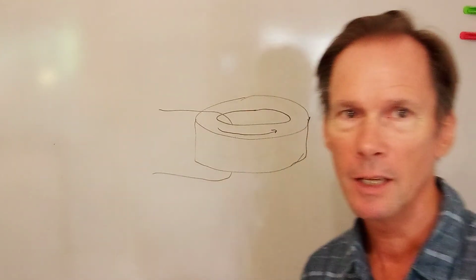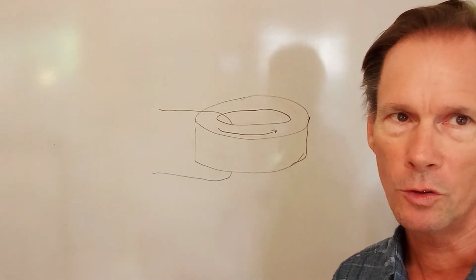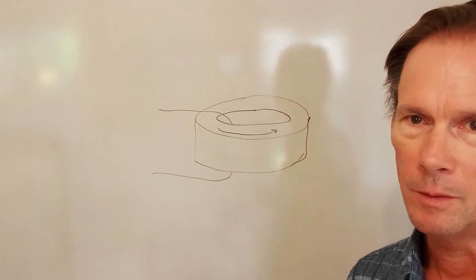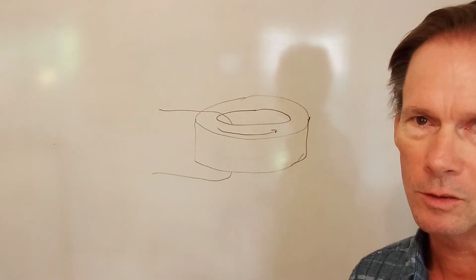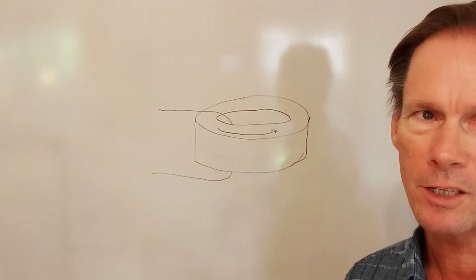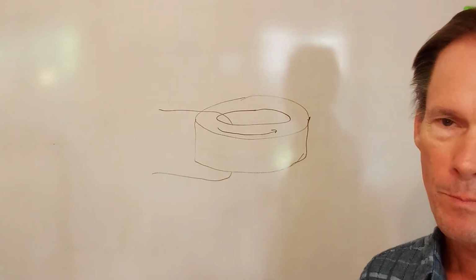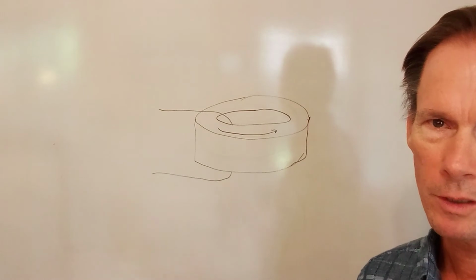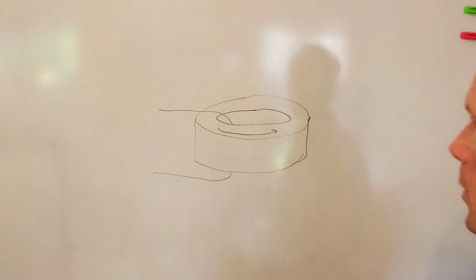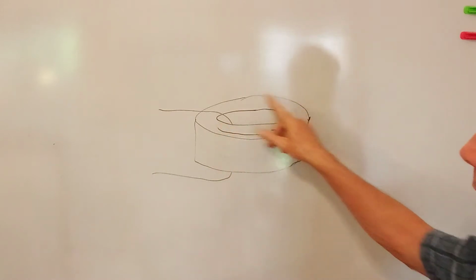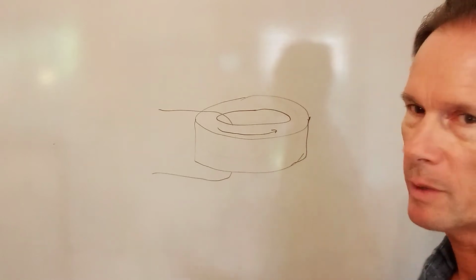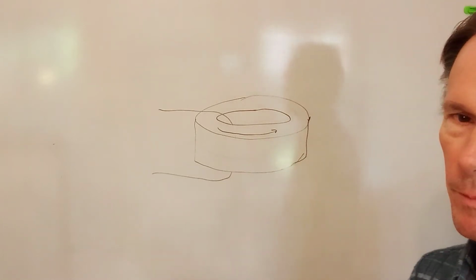Magnetic materials have two types of permeability and magnetism. One is what you normally describe as the real permeability, and then you have imaginary permeability, which we don't usually deal with until you get up at really high frequencies. The real permeability is just what you get around, in this particular instance, the interior of the toroid.